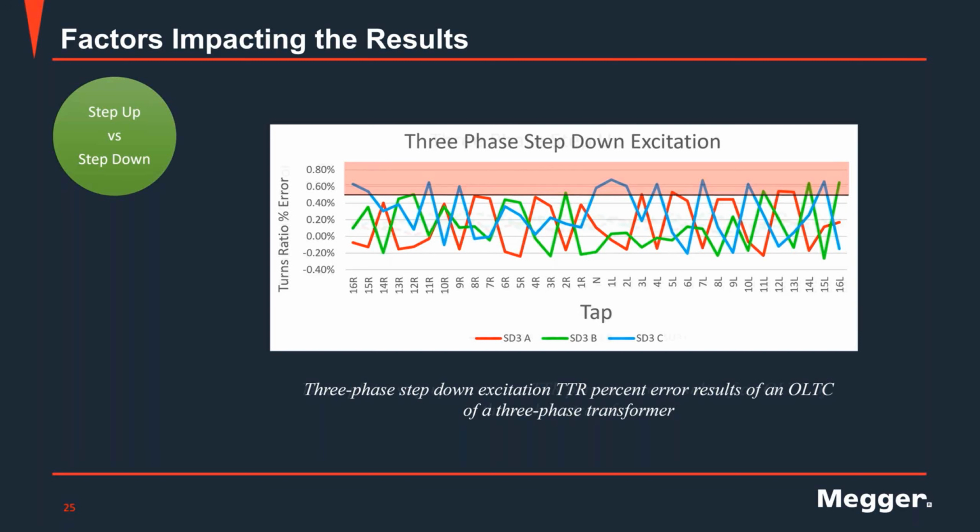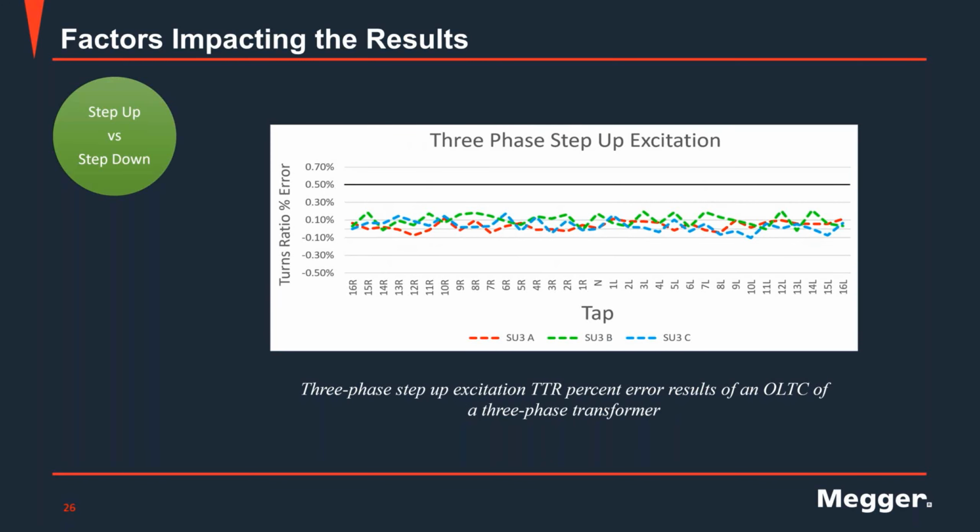Let's look at the same test using step-up excitation, energizing the low voltage side of the transformer. We see the error is very small compared to the previous result.